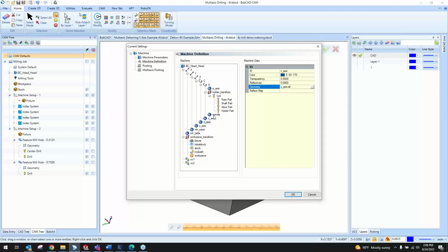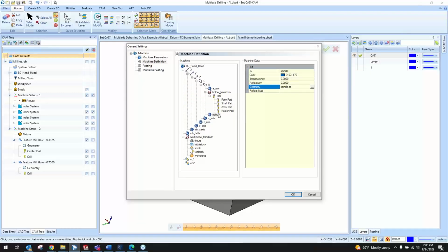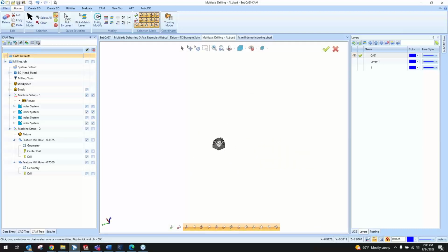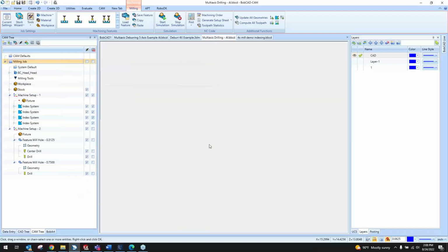And so when you go in, you can click on this three dots icon to select a different STL file than what you have for the geometry of each one. And essentially you have it oriented here in the CAD workspace according to where it will be in your simulation. So that's very basically how you can create your own machine in simulation.